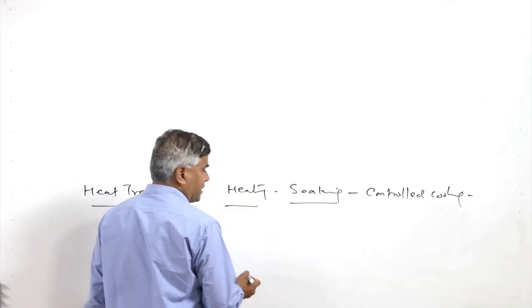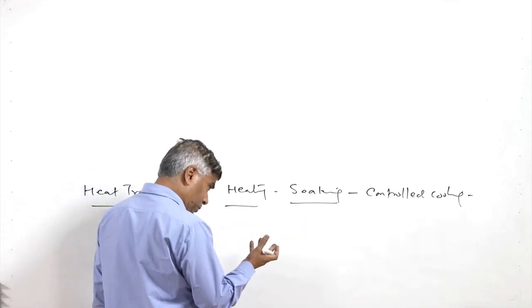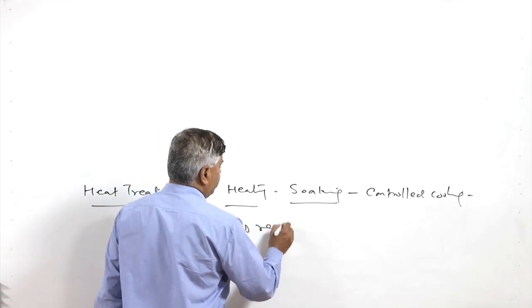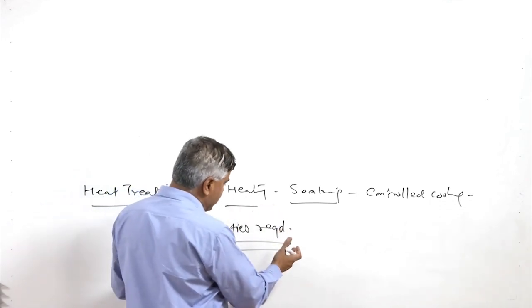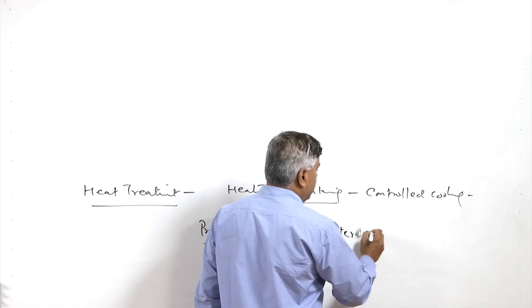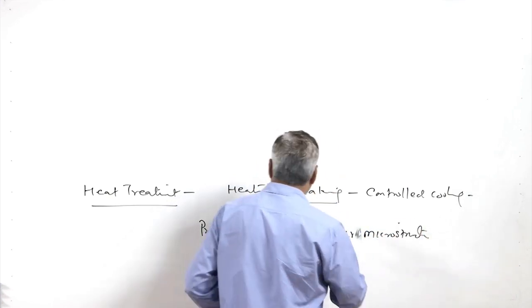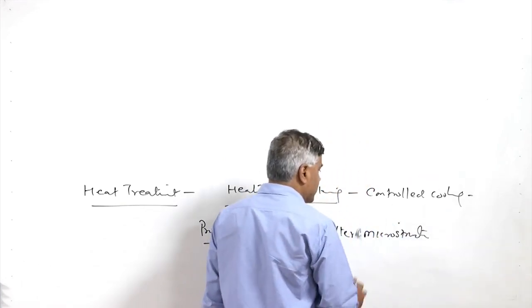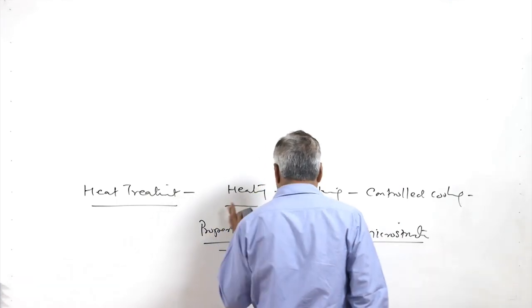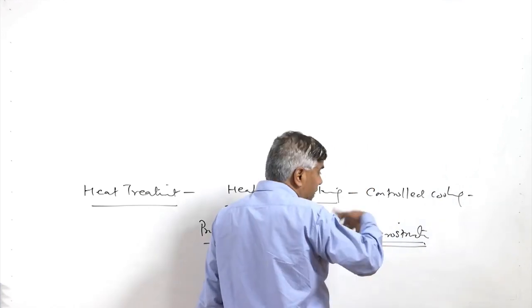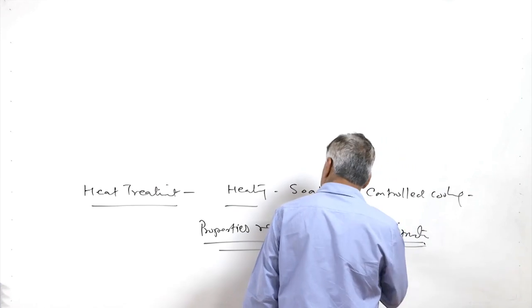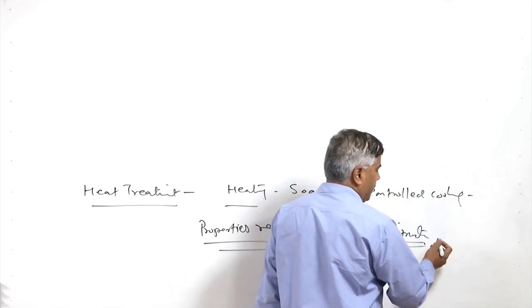Depending upon the kind of metal systems, there are different types of heat treatments, but the general approach in all of them is simple. For a given functional purpose, the properties needed are identified, and based on the properties required we try to alter the microstructure of the bulk material through controlled heating and cooling cycles, so that we have the desired structure and so the properties. Altering the microstructure is one of the main approaches in heat treatment, wherein we realize the desired combination of properties or property enhancement in the bulk material.